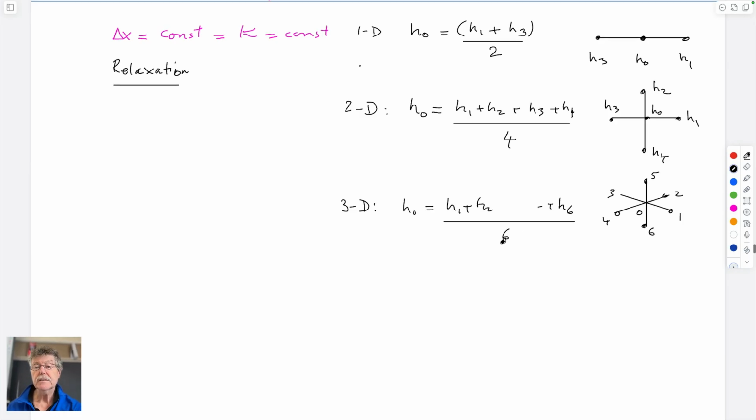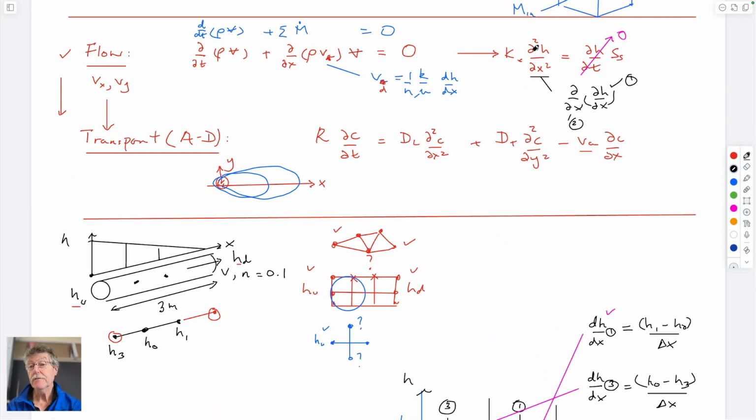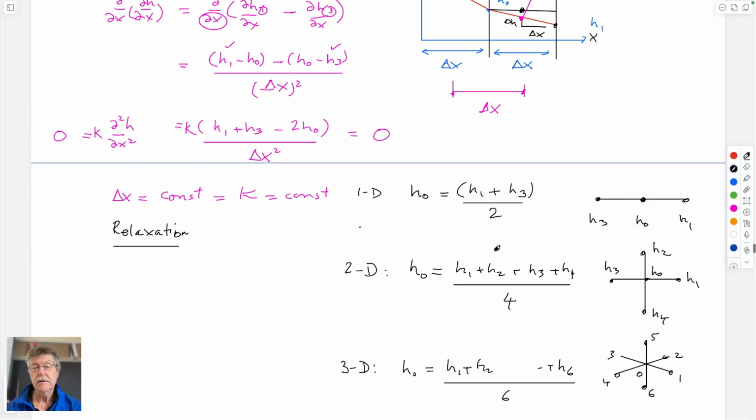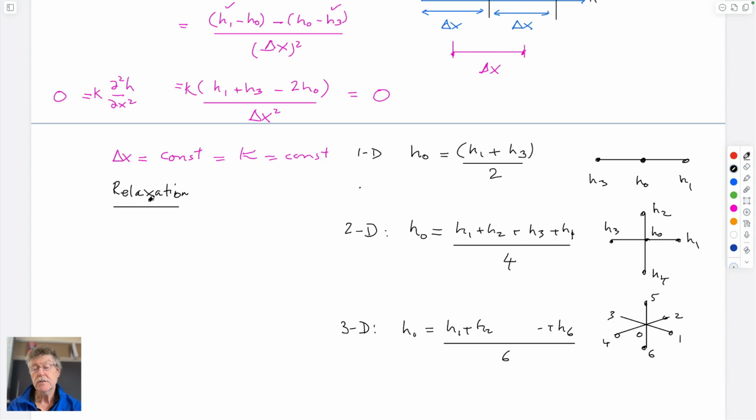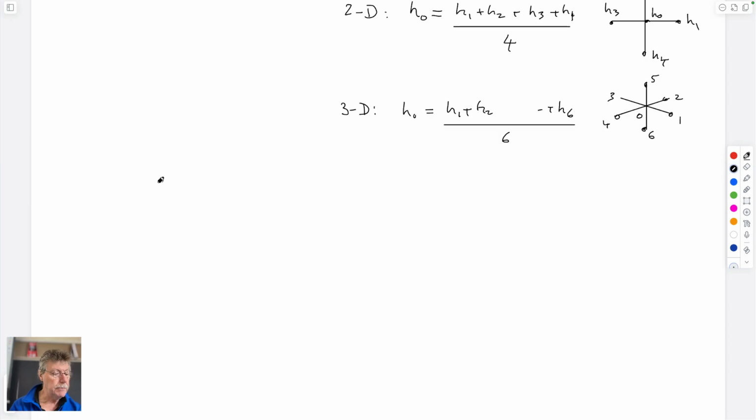So all we're doing is taking these equations, making them into finite derivatives, and then using finite differences to be able to compute it. And the method by which we kind of advance towards a solution is called relaxation, because you just successively reduce the errors, and this guessed value for the inner head slowly asymptotes towards the magnitude. So this is a fun class. I like this. So we'll do an example.